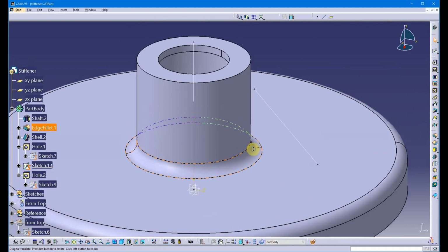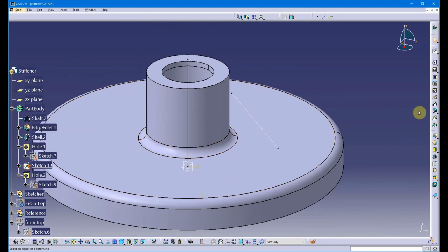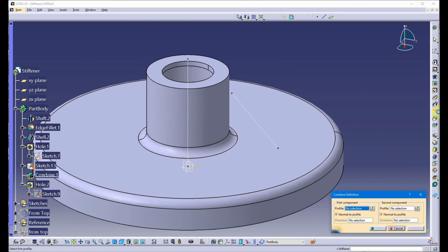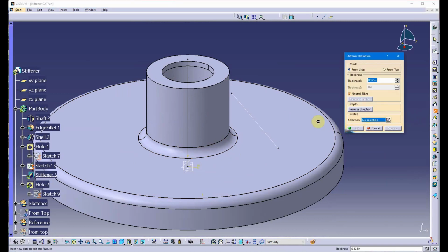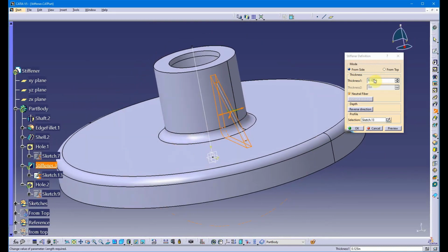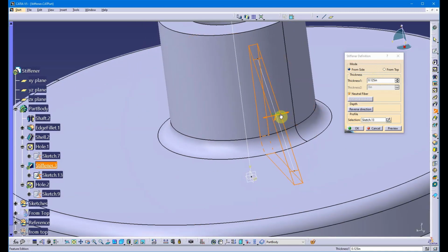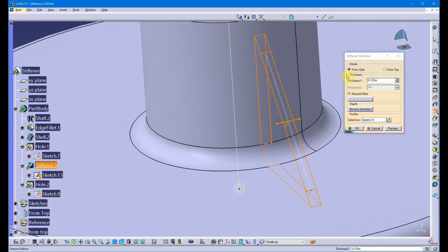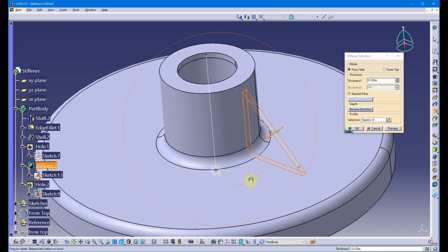It's going to have neutral fibers selected, and by default you're going to have merged ends. So let me go to the stiffener tool. Typically you can find it on the sketch tools toolbar. It may be behind the solid combine tool, so go look behind the solid combine tool. This is going to be what I add stiffness to. I'm going to go with 1/8 of an inch thickness, neutral fibers selected by default, and that's what's happening. It's going both sides, and I'm doing from the side. From the side will currently merge with the existing solid in the current body.